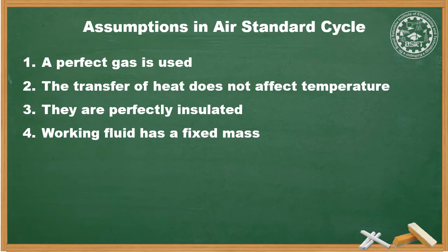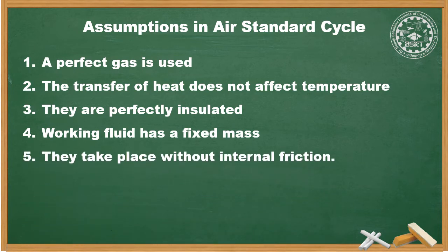the working fluid has a fixed mass. The working fluid has a fixed mass and does not undergo any chemical changes throughout the cycle. This states that the working fluid has the same mass throughout the working cycle. Fifth, they take place without internal friction. This is the most important assumption in the air standard cycle, that is, they take place without internal friction, as it is not possible in a general IC engine to work without internal friction.